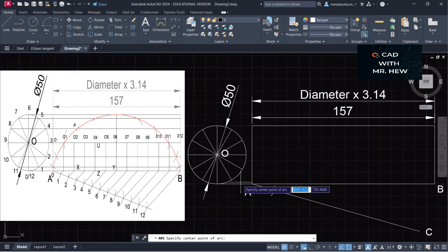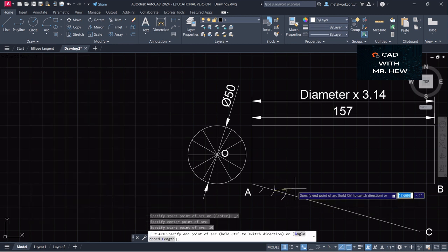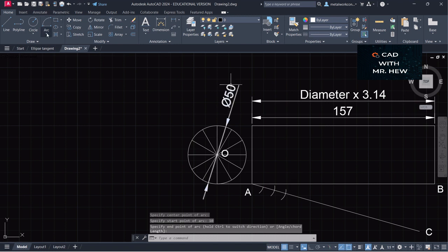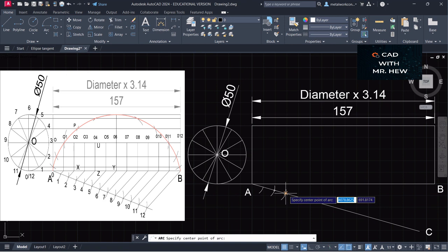So you would open your compass to any radius. 10 millimeters is a good radius. Enter. All right. We'll come again. So you're going to use the same radius that you used to mark the first one, which was 10.